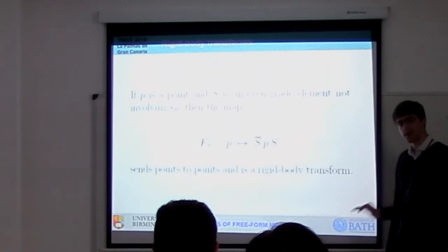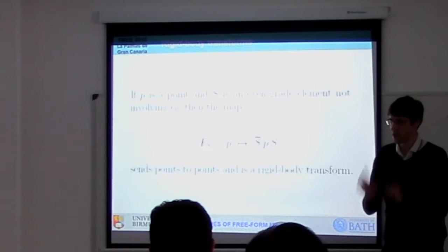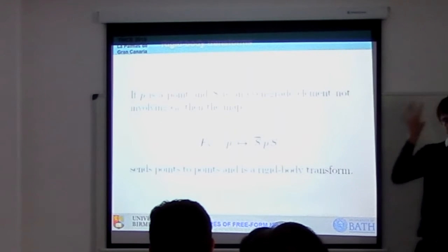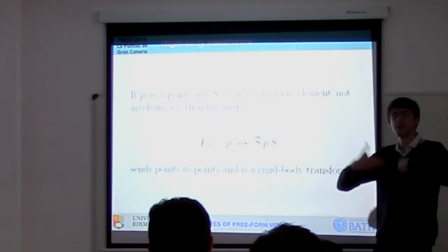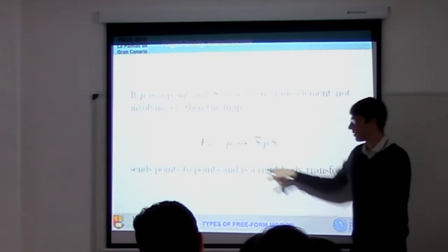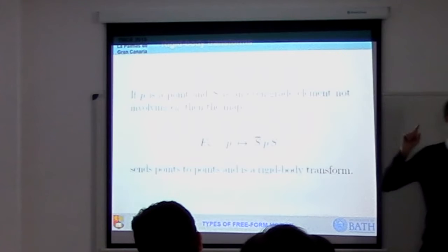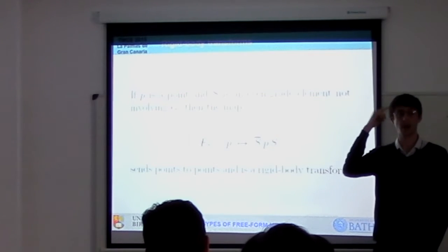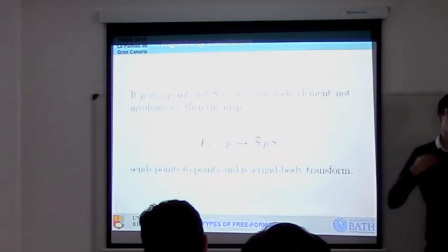But the thing that we're really interested in here is how we're going to perform a rigid body transform. If you take any even grade element, by which I mean anything in the geometric algebra which, when you measure the grade by the number of subscripts, happens to be an even number, then this will correspond to a rigid body transform using this map here. So when I'm thinking about a rigid body transform, I can represent that not with a matrix now, but with this thing called an even grade element, which, practically, is just a list of 8 numbers, like 8 coordinates, if you like.